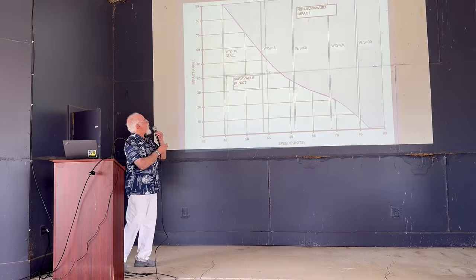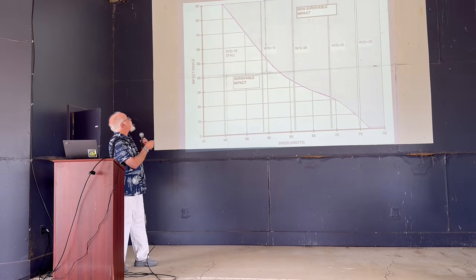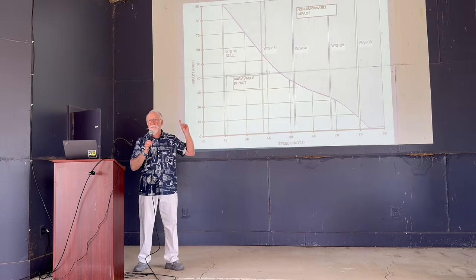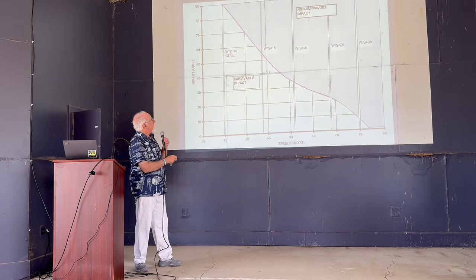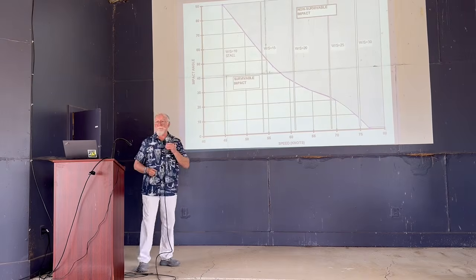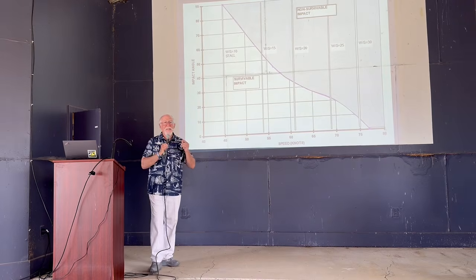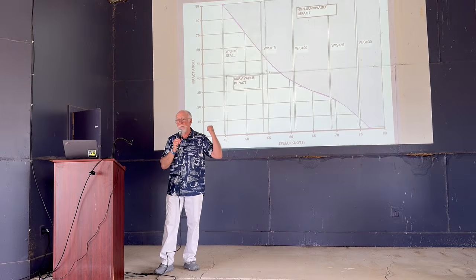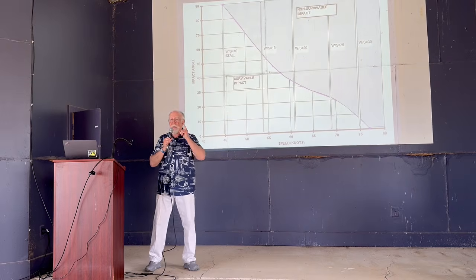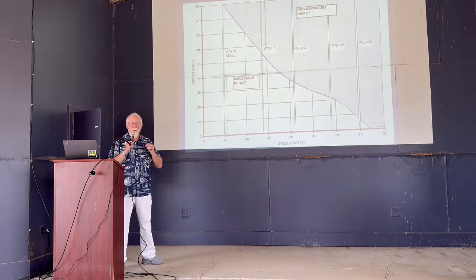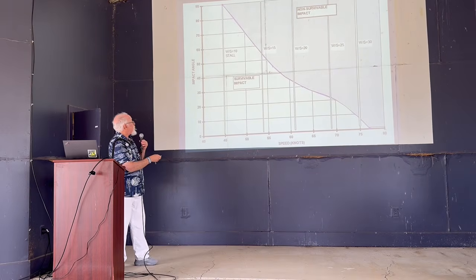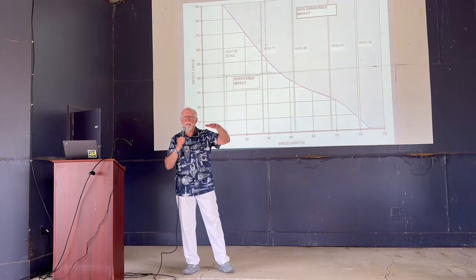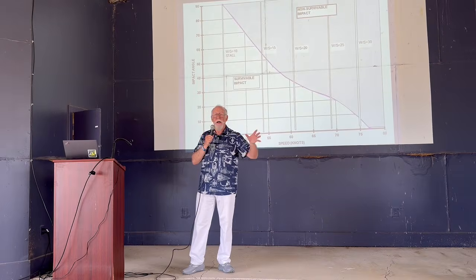First thing is that 45 knot stall speed that Light Sport and Mosaic talk about, it's not irrational. If you look at it, what that 45 knot speed is saying is, by the way, if you're above the curve, you're dead. What that says is at 45 knots, unless you fly into a brick wall or impale yourself on a flagpole, you'll probably survive. That 61 knot speed for Part 23 is not irrational either. That's about a 30-degree impact. Well, guess what? At stall, if I keep it a little bit above stall, what it's telling me is if I keep the airplane under control and just glide into the ground, I'll probably live.